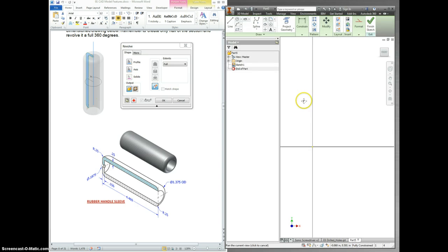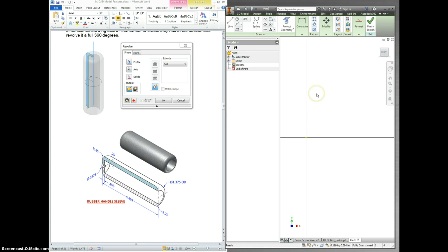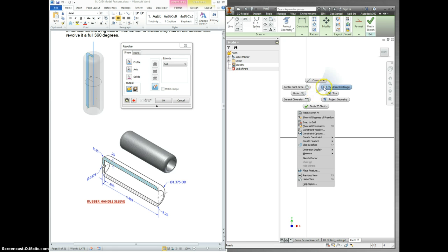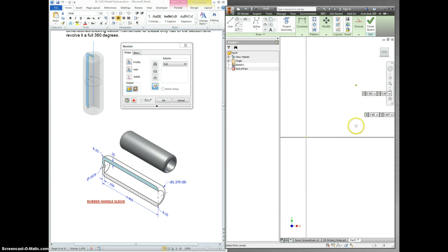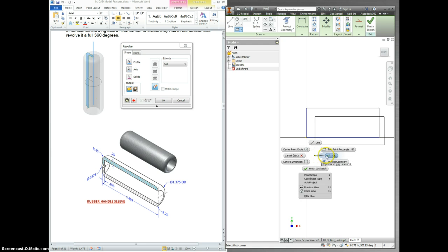We're going to make a new sketch. I'm going to show you a lot of tricks really fast. So first off, right click. There's your 2-point rectangle button, and we always want to start in the center of this origin here. Now the way that I visualize this with the L shape is that, well, I don't want to spend the time making this with lines because that's kind of difficult. So I'm just going to make 2 rectangles. Right click and say OK.